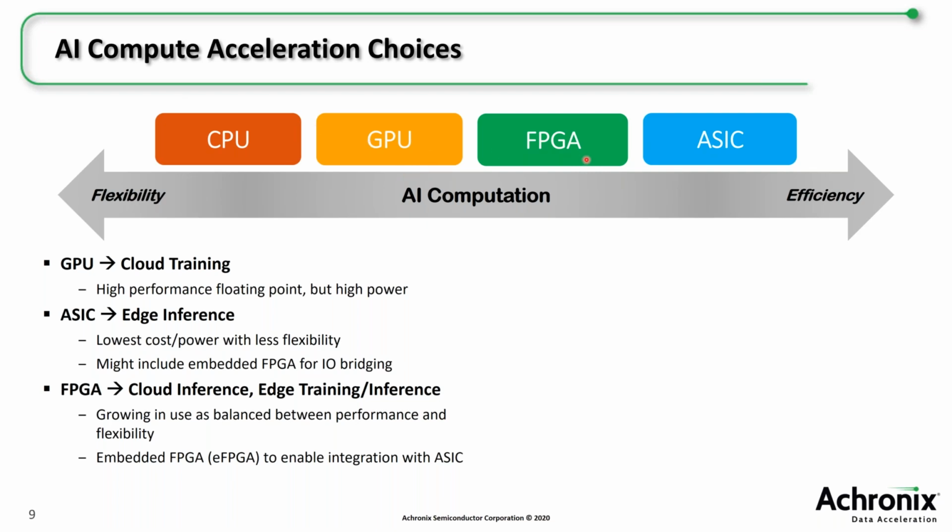Now, particularly with looking at this block floating point area, it's tough to do it with GPUs and CPUs just because they tend to be optimized for single, even double precision floats, sometimes having integer arithmetic starting to be introduced there. On the other extreme, ASIC blocks give you great performance in terms of teraops per watt, performance per watt. The challenge with the ASIC is, unless you've envisaged exactly the correct number format for a new type of algorithm, you probably haven't prepared it already.